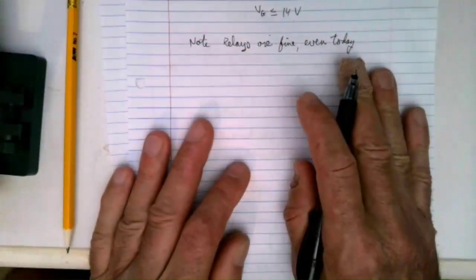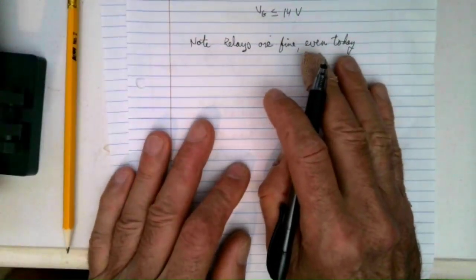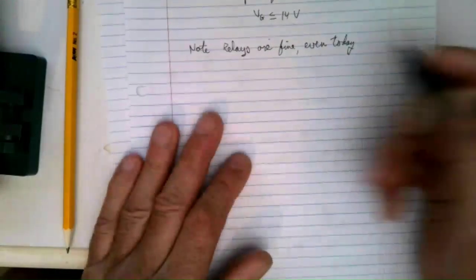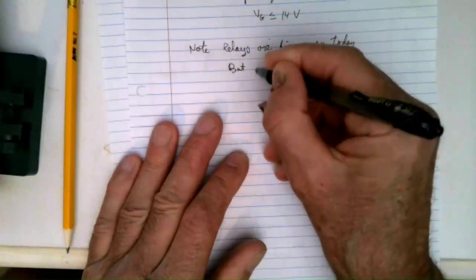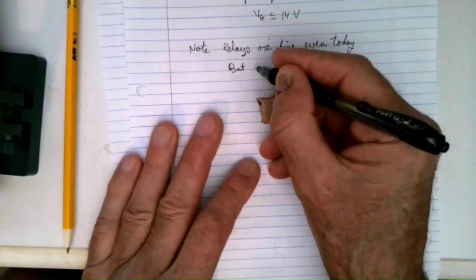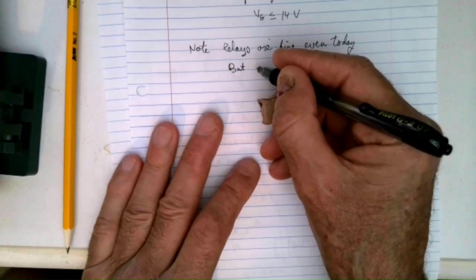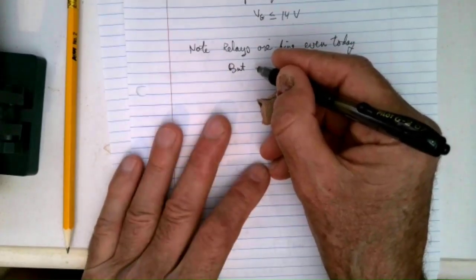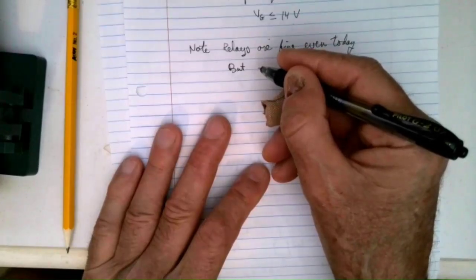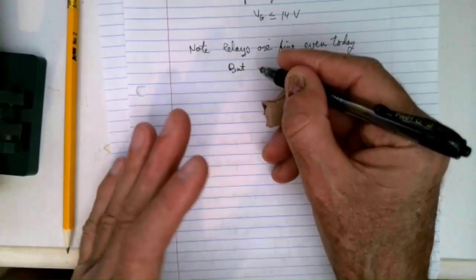Okay, relays are fine even today, and there are thousands of different kinds of relays: heavy duty, light duty, small, but you cannot duty cycle them. If you want a PWM, or if you want to try to do motor speed control or something like that, you cannot toggle a relay 1,000 times a second, or it won't last. Won't last an hour. They're not designed to. But if you want to turn something on and off every 10 minutes, a relay may last longer than the semiconductor equivalent, although they do have a finite lifetime.